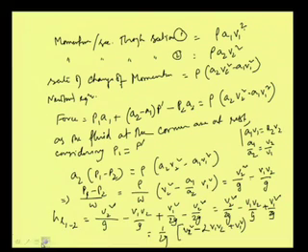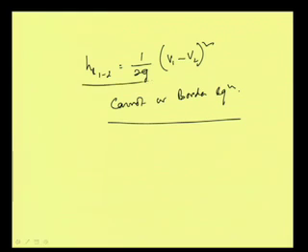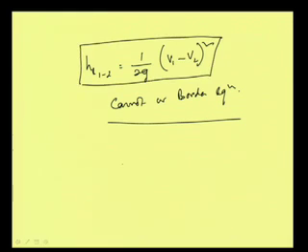Well, I am writing this expression here, that head loss from 1 to 2 can now finally be written as 1 by twice G times (V1 minus V2) whole square. This equation is known as the Carnot or Borda equation, because they derived it. This equation is popularly used for computing the head loss due to sudden expansion.